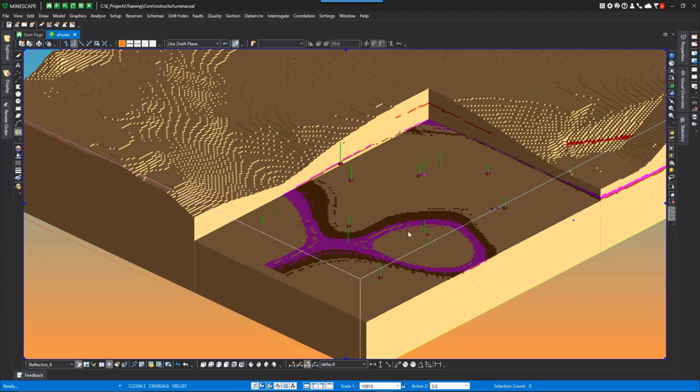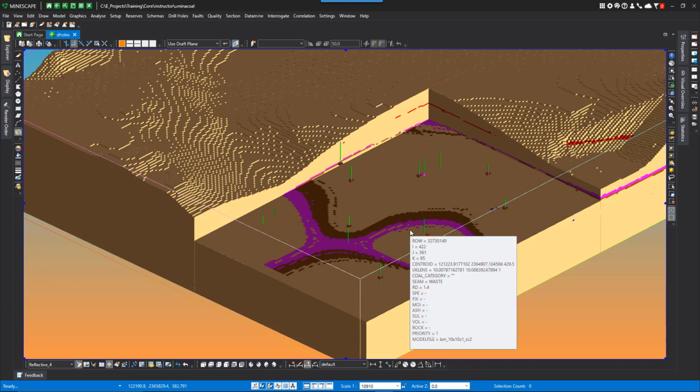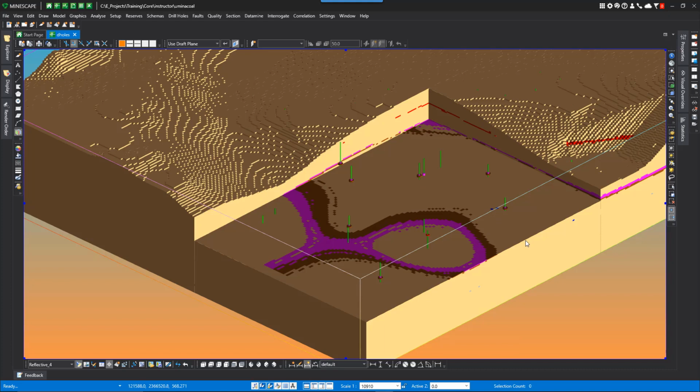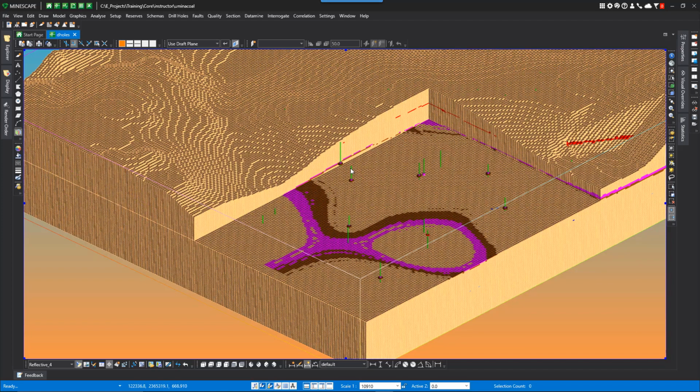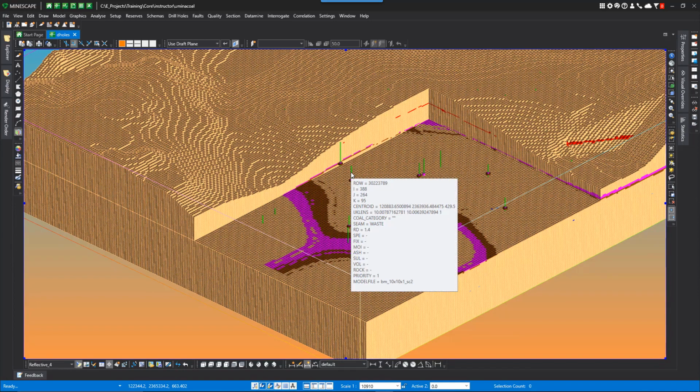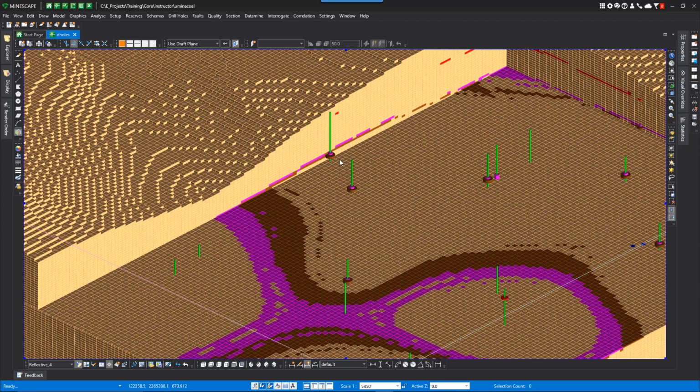As you can see, anytime you access the slicing function, you can slice in any one of the I, J, K, or planes by just selecting the colored ball and moving your mouse. You can also display the cell edges by right mouse show cell edges. You can also zoom in to get better detail of the subcells.